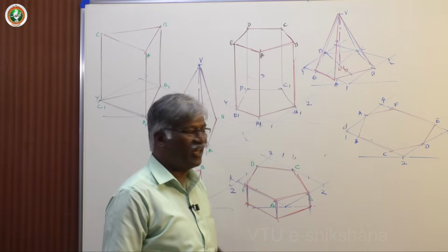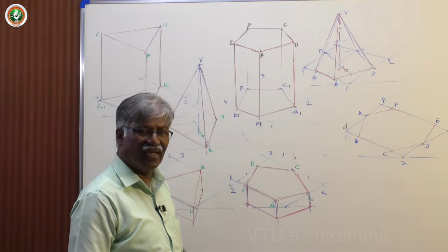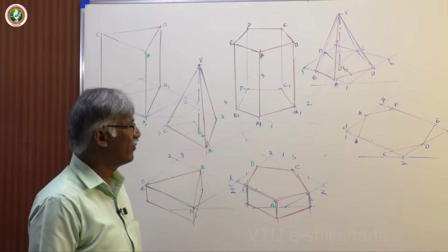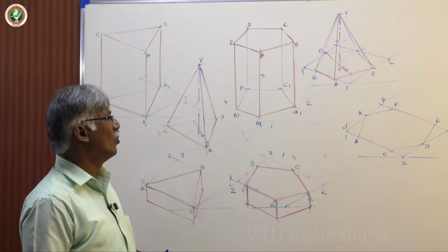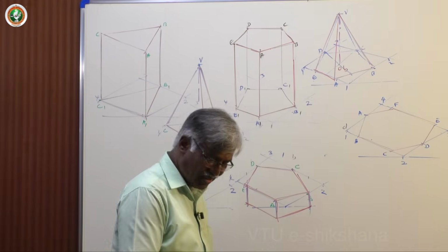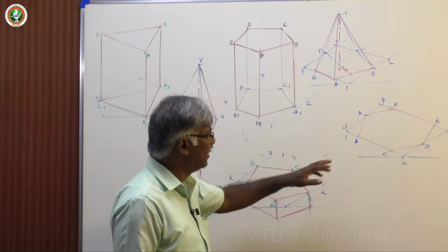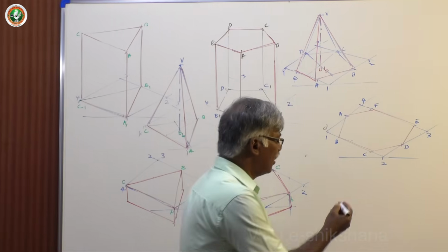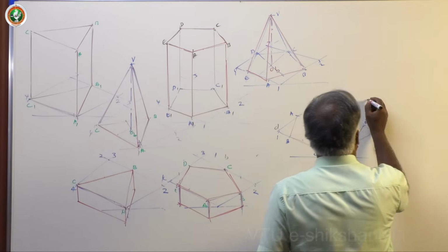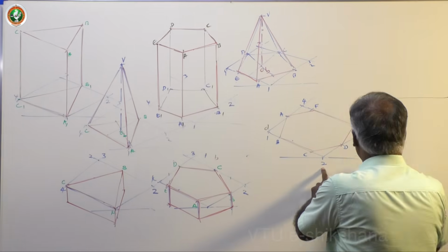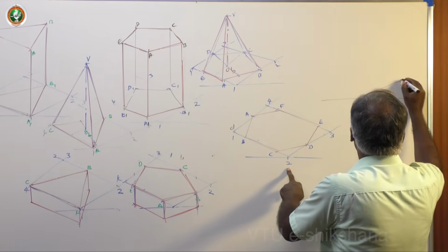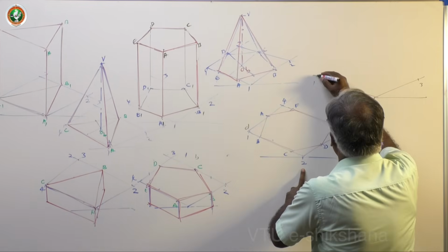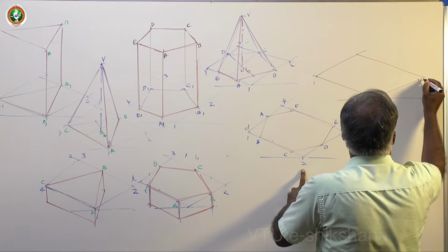Now finally let me take the hexagon. Majority of the time you get these two shapes, more number of times repeats. So hexagon, again it's a symmetrical figure in both the axes. How to draw the prism? It's as usual, you have to keep this 2 reference, then 2 to 3, then 1 to 2. So as usual you have the rectangle for this.